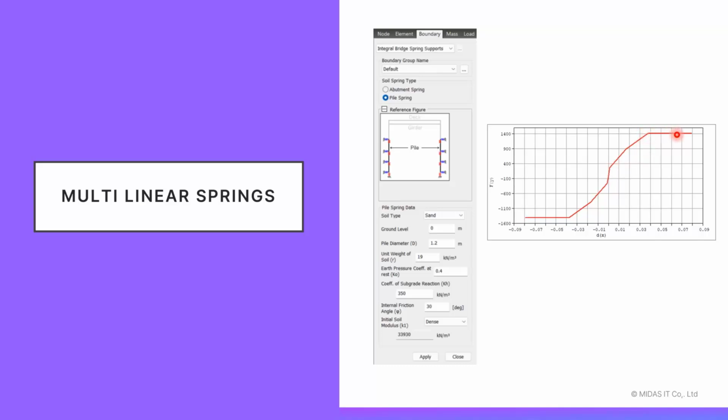Later on, after the yielding point, it's perfectly plastic, a kind of pure plastic material, like a Mohr-Coulomb material kind of thing. This kind of stiffness is provided to the soil spring. So this is the multilinear springs procedure. There are many methods that help in determining the multilinear springs, like BM, Lehane theory, and so on. These methods are again classified, with different methods for soil and different methods for rocks as well.